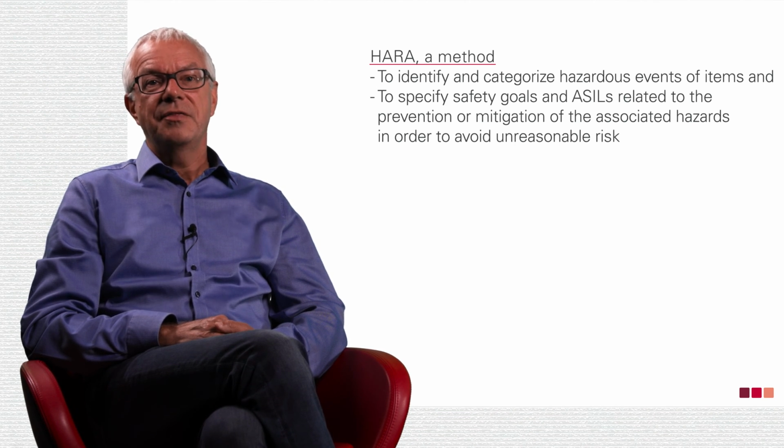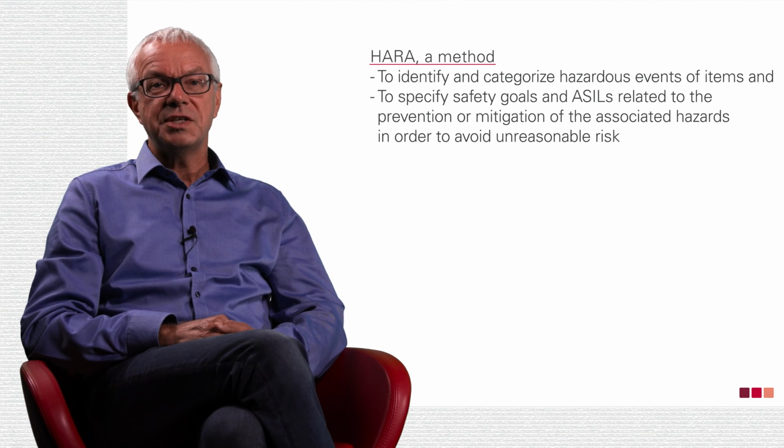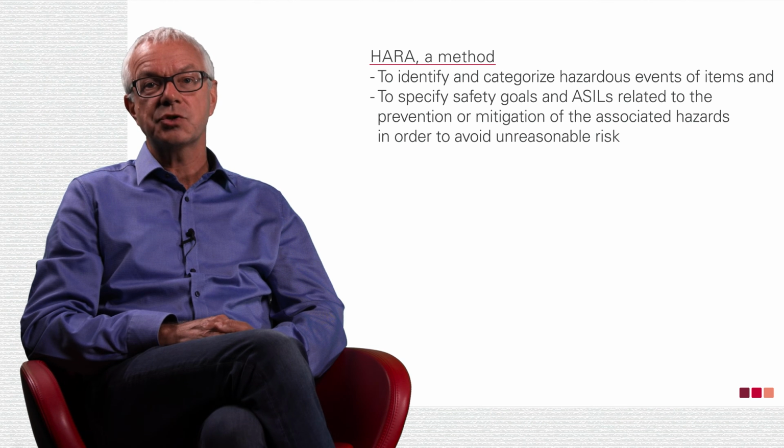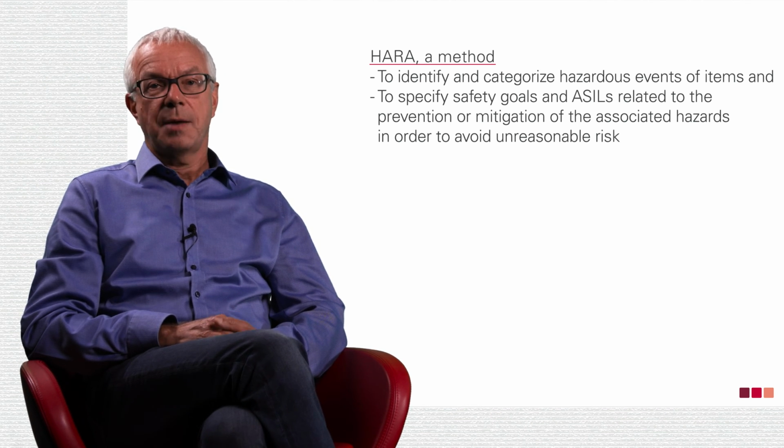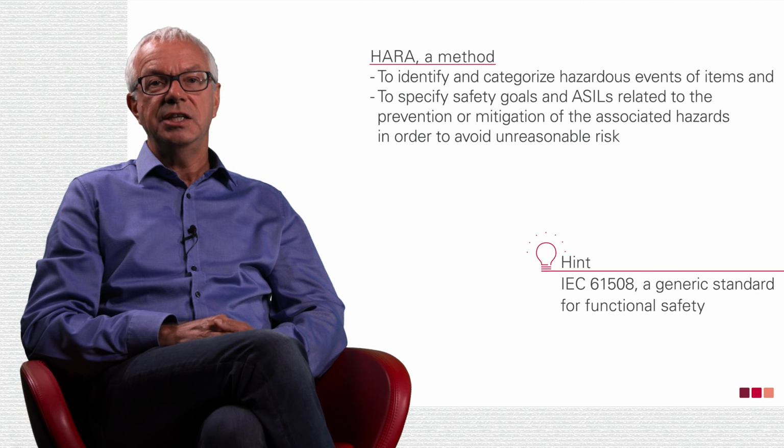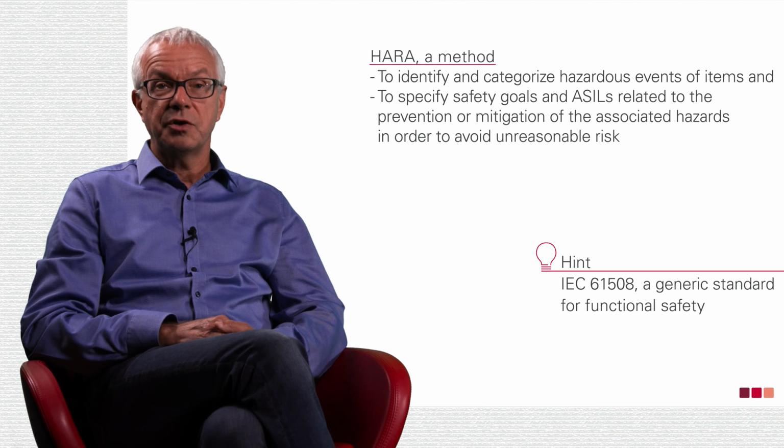Please note that in the automotive sector, you always use exactly this HARA term and this designation because it precisely describes the prescribed procedure. For example, if you used the widely used term hazard and risk analysis, other people would probably think you mean the requirements contained in IEC 61508, which are not specific to the automotive industry.